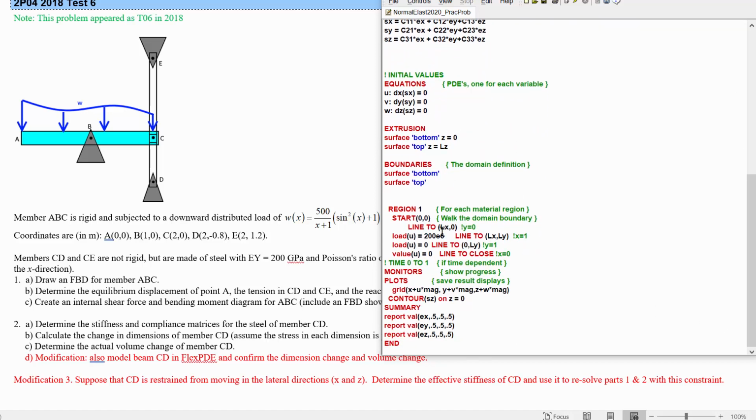I don't think we need to change. Oh, we need to change the stress. Right. So what do we have? We have a load on the positive and negative Y faces. So when Y equals 0, we'll say that there's no displacement there. Value of V is equal to 0, and we'll leave everything else the same. So we'll put no condition in for U or W, defaulting to the default no stress in X and Z.